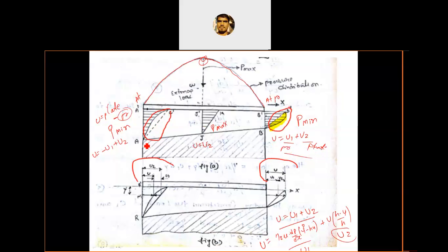Because of the moving surface and the taper, the fluid is forced to move from left to right. Because the cross section is reducing, it is converging, as we already said. As the area decreases, the velocity increases, because the same amount of fluid flows through less area. Some of the fluid will flow back, creating a negative velocity at the entry. And at exactly the middle, the velocity is equal to only the plate velocity.